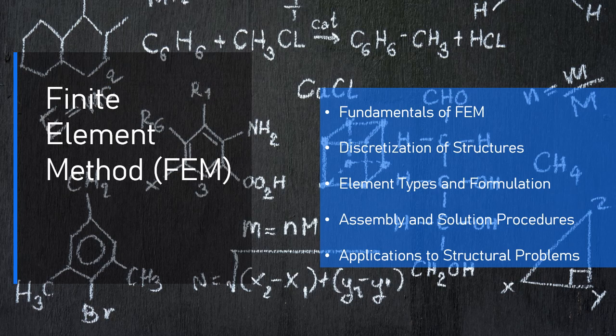Benefits: allows for the evaluation of resonance frequencies, which can lead to amplification of seismic waves if matched with the structure's natural frequencies. Can predict local failures, e.g., floor collapse, wall cracking, or global instability, e.g., building overturning. Helps optimize damping systems, e.g., tuned mass dampers, to reduce the structural response during earthquakes.